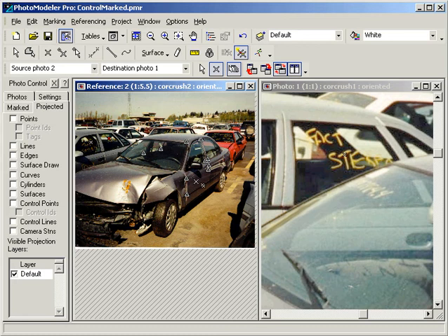Similarly, with a road scene, you should be careful that features you are surveying for use as control points have not been moved since the time of the original photographs. The survey of control points is usually done after the fact, and you want to be sure that you are getting the coordinates for the objects that were in the same position at the time the original photos were taken.